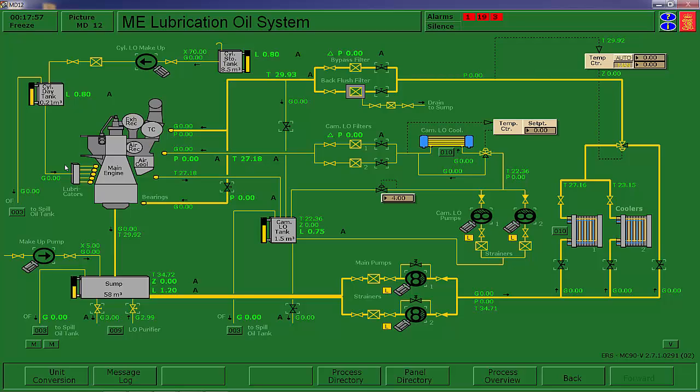So you have to supply lube oil to lubricate the liners. And that is a measured amount of oil, and it is delivered through injection points around the cylinder. This is one of the biggest advantages of a slow speed engine, because when burning high sulfur fuels, you can use a high TBN oil, usually a TBN of about 70, to neutralize any sulfuric acid that is created during the combustion process because of the sulfur in the fuel. In today's world, it's about 4% sulfur.